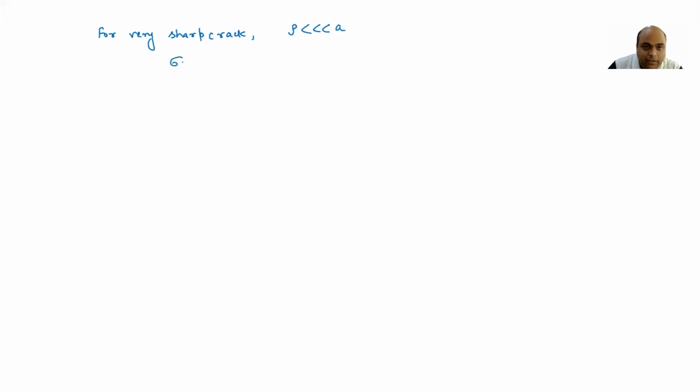So we can write as an approximation sigma tip as 2 sigma root over A by rho. Okay. Now see, A here is not the full crack length. A is your half crack length. So again, don't make a mistake. A is different than 2A. So 2A was the full crack length and half crack length is your A.